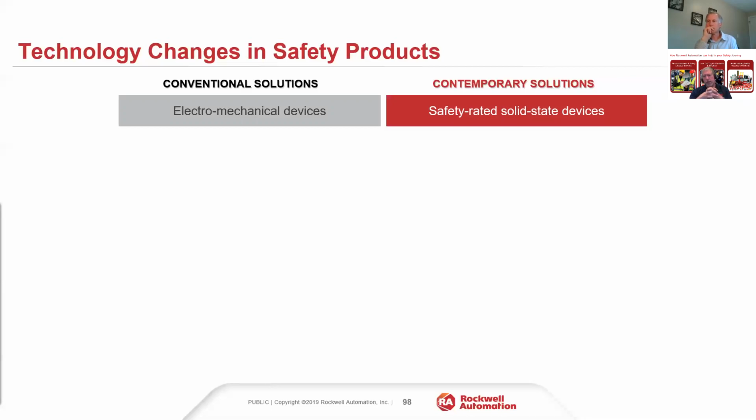So on the other hand, when you look at a solid state device, the MTTFD, the mean time to dangerous failure, is not operation dependent. It is design dependent of the actual switch, and it is provided to you as a number by the manufacturer. So if nothing else, moving from electromechanical solutions to the solid state OSSD type solutions simplifies the implementation of today's safety standards. And we'll go through that a little more later, but I wanted to talk about that a little bit now.